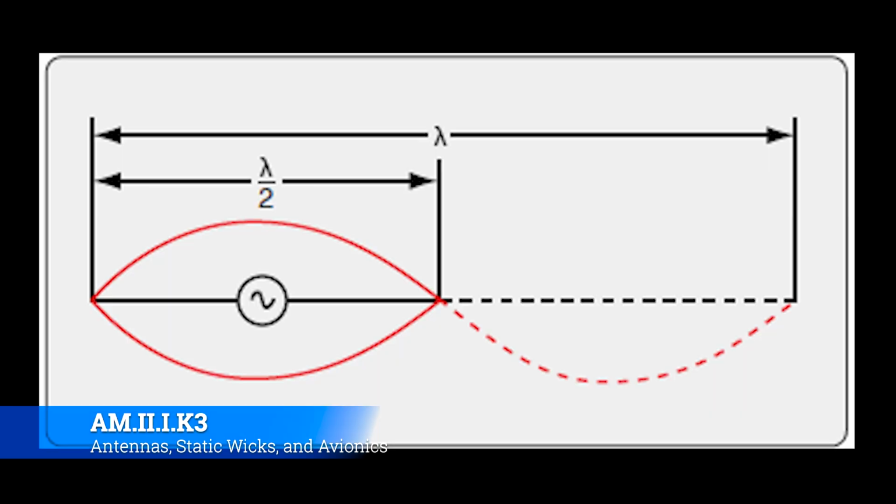Okay, let's pretend you're an engineer and you're going to select an antenna to go on the end of a transceiver and get mounted to the top of the fuselage, so that way you can transmit out. What are some of the things you're actually going to think about? There are three main characteristics you have to pay attention to when selecting an antenna, or whenever you're simply operating an antenna. You have to make sure you have the right antenna that has these three factors optimized for its use. One is length, the second is polarization, and the third is directivity. Those are the three fundamental traits of any antenna.